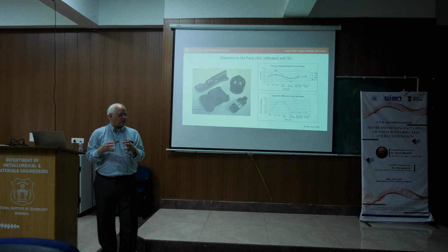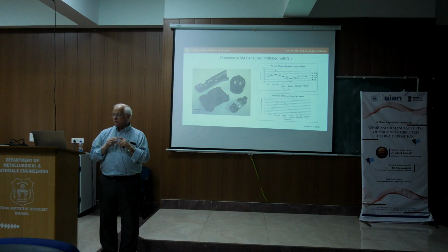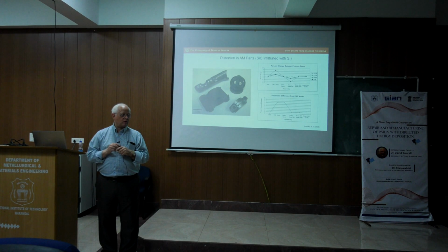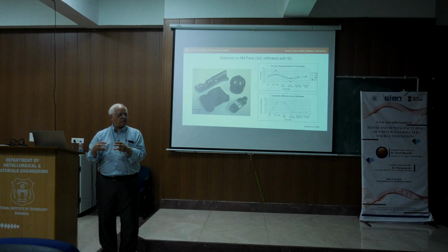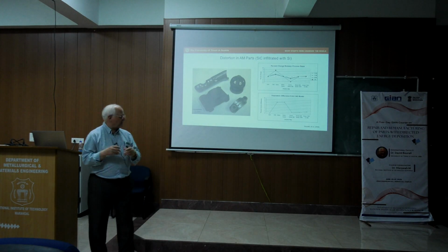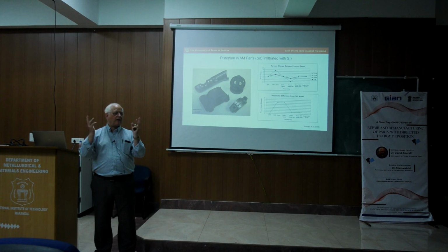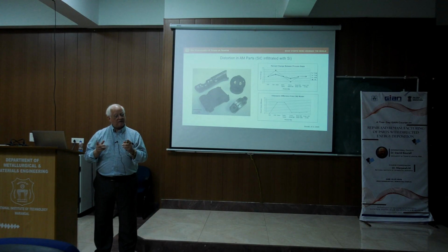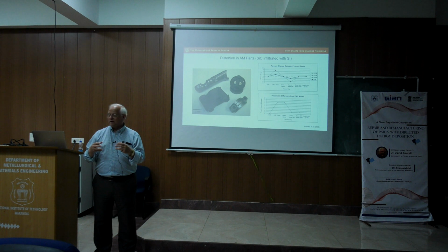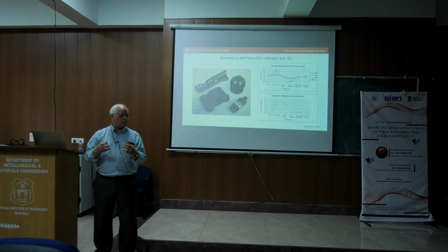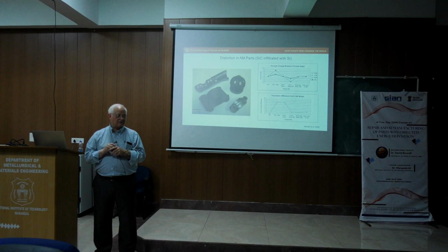Once the phenolic was cross-linked, we could heat it up to a high temperature and burn off all of the polymer. But the phenolic, after being cross-linked, doesn't melt, so it keeps the part from falling apart. We're talking about 700 degrees centigrade or so, 800 degrees centigrade. The phenolic and the epoxy all burn off, but because it's a high ash material, what it leaves behind is carbon. So now we have the silicon carbide held together by carbon, which is what we call the brown state.